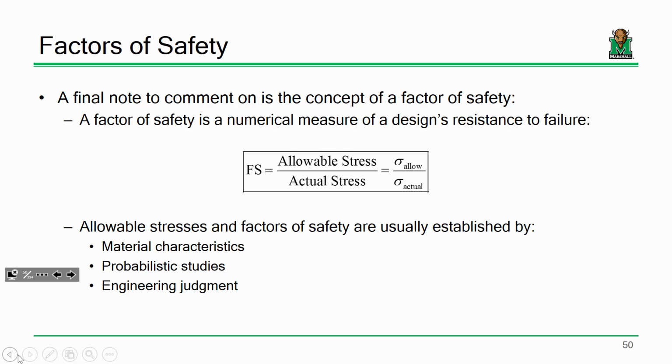Are you telling me this has got the exact same material characteristics as this? It's wood. Wood is a very orthotropic and variable material. There's going to be uncertainties with the manufacturing process. You're telling me these holes are drilled in this table in the exact same spot as these? No, come on. No. There's a little bit of variability, okay? And because of that, that creates uncertainty, and uncertainty leads to the use of factors of safety.